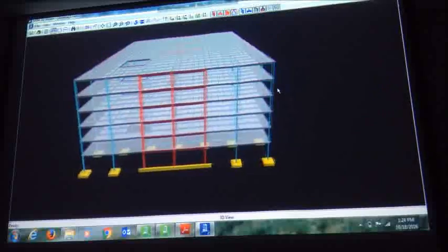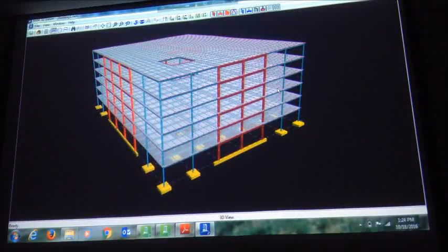Can you repeat again, why did you change the size of the columns? Usually that's in practice we do that. You change after what level? Columns, it's still members, right? So it's still members comes around like 40 feet, 30 to 40 feet, 45 feet. The reason is only that you have to use 18 wheelers to bring it. So they have a limit on their space, about 40 feet. So 40 feet means you have like a 15 feet first floor, 12 feet, another 12 feet.